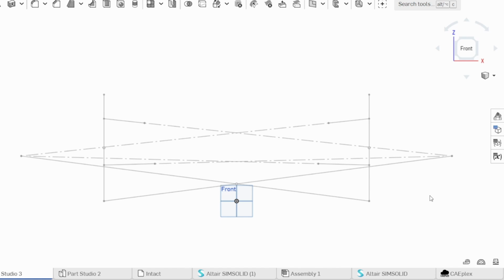So it may say you get 100 pounds more weight transfer from changing your roll center from, say, 1 inch to 2 inch. It may not actually be 100 pounds in real life, but there will be an increase of some kind, and you can use that to tune, which is good. It's real simple, it's quick. With jacking force, you get the same thing, but you also get the vertical component, the Z, so you can find the ride height change of your car.